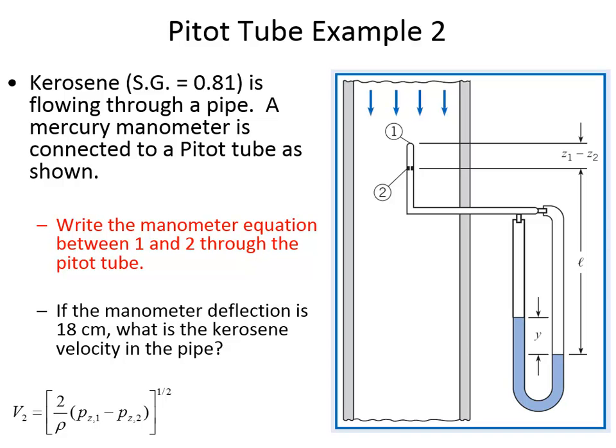Next, we just jump straight from this interface over to that side without any change, since we're moving sideways through a static fluid. The pressure doesn't change at all. So now we're here, and we're going to go up the distance y through the unit weight of mercury. So minus gamma of mercury times y, and then minus, now the distance is a little bit tricky.